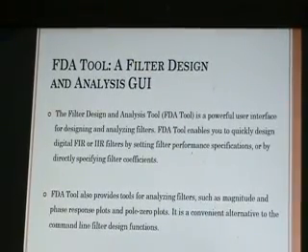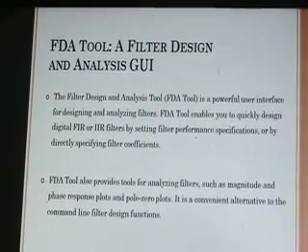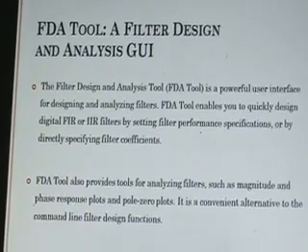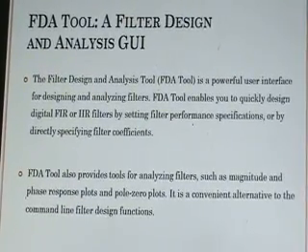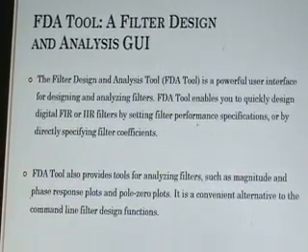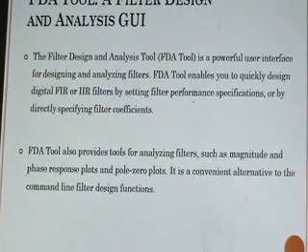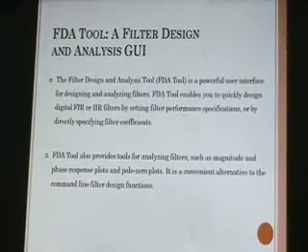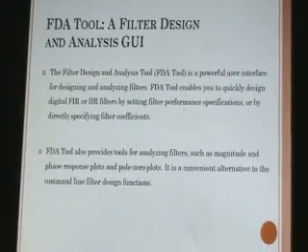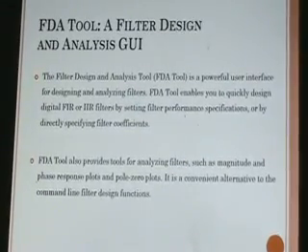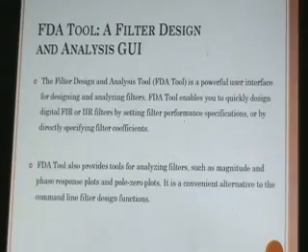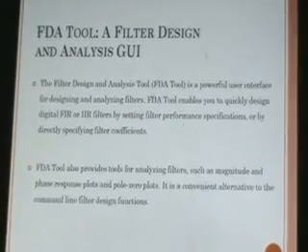FDAtool enables us to quickly design digital FIR or IIR filters by just giving the filter performance specifications or by directly specifying filter coefficients. FDAtool also provides tools for analyzing filters such as magnitude and phase response plots as well as pole zero plots. It is a convenient alternative to the command line filter design functions.